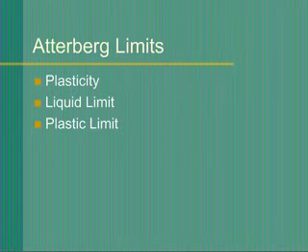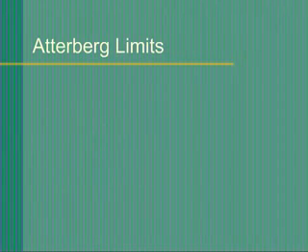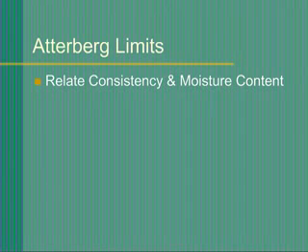These tests are important in the classification of fine-grained soils. In particular, the liquid limit and plastic limit are used to distinguish silts from clays and to classify the plasticities of silts and clays. Atterberg limits tests quantify the relationship between the consistency of a soil and its moisture content.